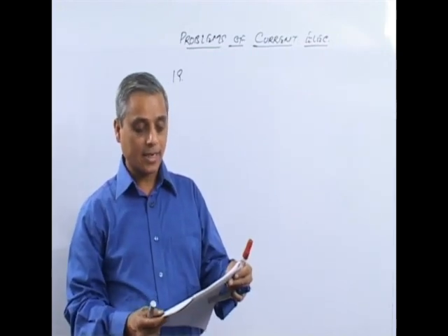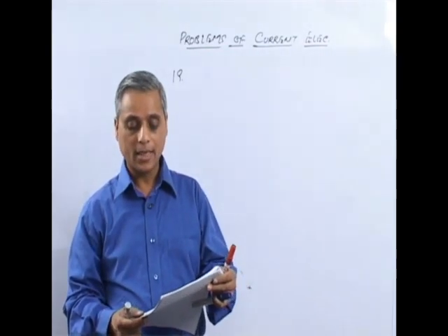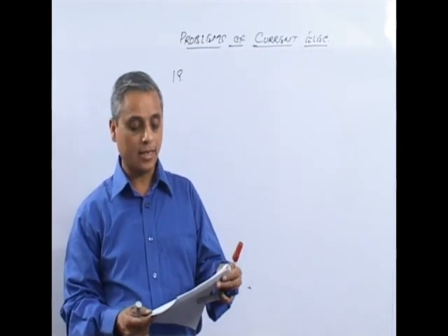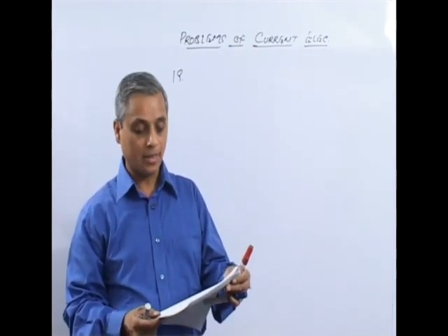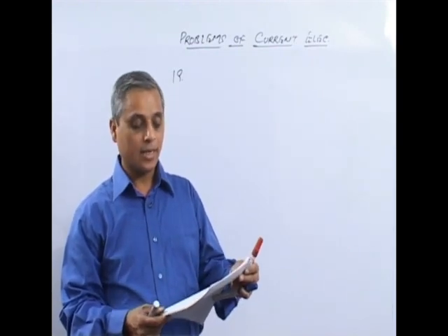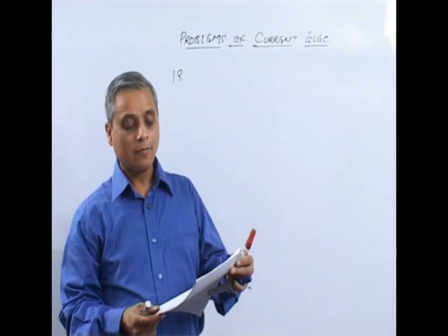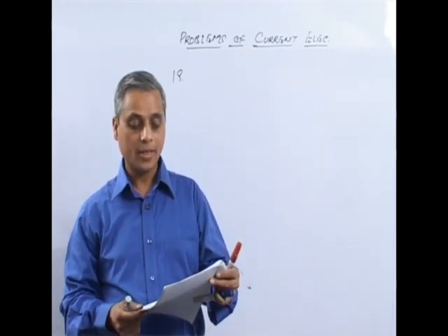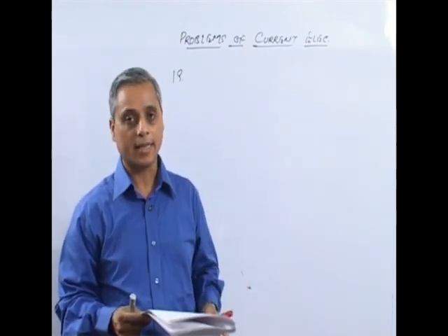The arrangement is connected in series with an ammeter, and two cells which are in series; the current is 3 ampere when the cells and battery aid each other, and it is 2 ampere when the cells and battery oppose each other. The number of cells wrongly connected is.